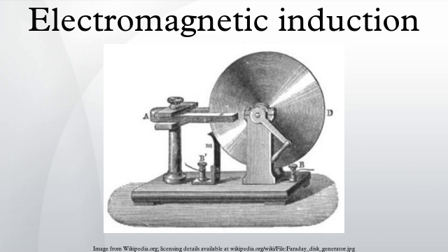A different implementation of this idea is the Faraday's disk, shown in simplified form on the right. In the Faraday's disk example, the disk is rotated in a uniform magnetic field perpendicular to the disk, causing a current to flow in the radial arm due to the Lorentz force. It is interesting to understand how it arises that mechanical work is necessary to drive this current. When the generated current flows through the conducting rim, a magnetic field is generated by this current through Ampere's circuital law. The rim thus becomes an electromagnet that resists rotation of the disk.